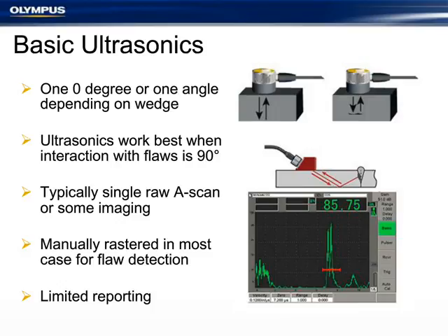It's really based upon the person doing the ultrasonic test to interpret that, try to characterize the defect by the echo dynamics seen in the A scan, and then use some gates and other things on the gauge to determine the depth and report it. So it can be very limited in some applications. It's just, like I said, really up to how well the person's been trained and his experience in the field.